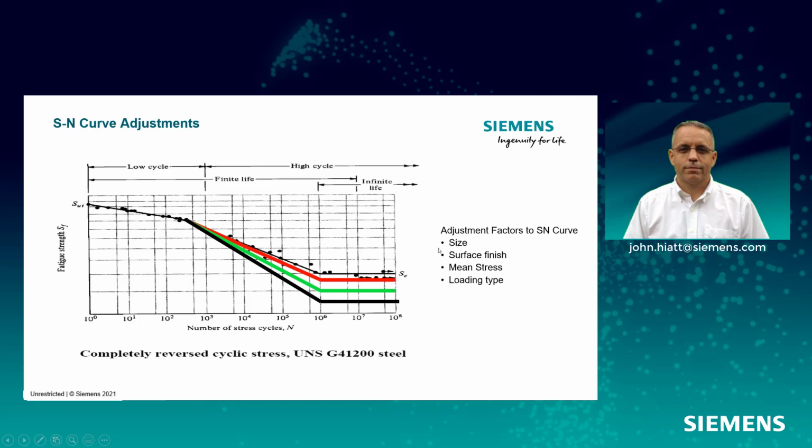So typically, these will have an effect. Think about a rough surface. A rough surface has more of a propensity to have some kind of imperfection that will crack when the load cycles. So if it's really rough, it'll form a crack before a machined smooth surface would. Size is a little bit confusing. For the same stress, a larger size has more surface area, more opportunity for imperfection. I didn't put all the slides in here because there's research to support this.